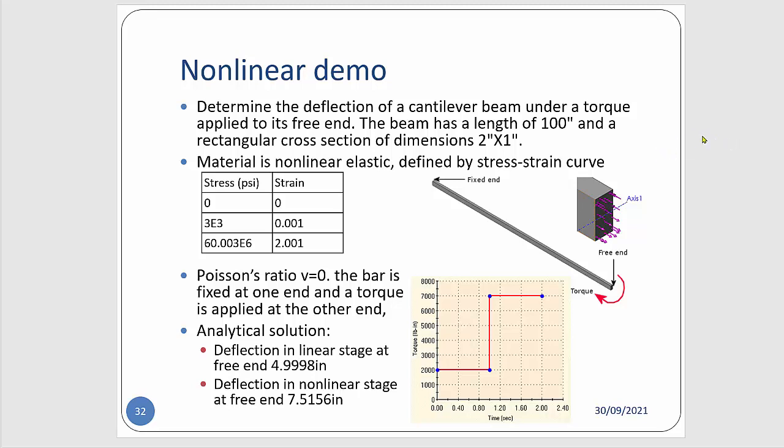In this video, we will focus on the nonlinear analysis, specifically the material nonlinear. Nonlinear analysis is one of the most challenging simulations in FEA. The material nonlinear is often associated with large deformation, and the material properties will not be constant anymore. For example, in structural analysis, the Young's modulus changes as the strain increases. So the Young's modulus will be defined by the stress and strain curve, which will be obtained from the experiment.